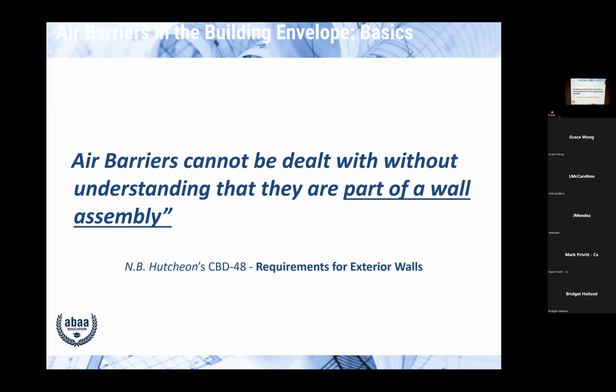Come April, you see a guy taking the insulation out in buckets because it's full of moisture. So then somebody says, well, what's the problem? Well, it's ventilation. We don't have enough ventilation. So we put more on. And there's a product called a turbine vent. Anybody know what I'm talking about? It's a whirlybird. That was one of the brand names. And you put it on the roof and it swirled. And as it whirled, it sucked air out of the attic. Problem solved.